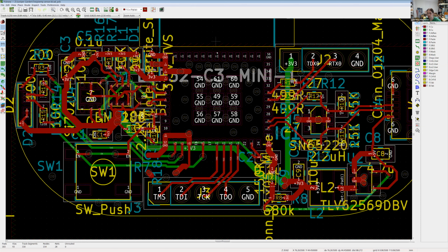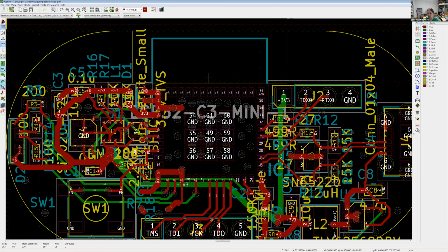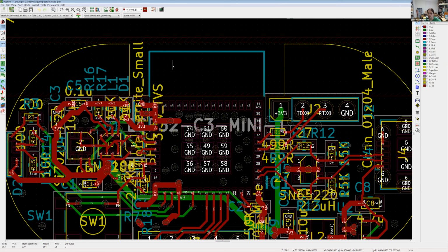The antenna, which is up here, it turned out that antennas have to have a clearance on either side of them so that they don't have any interference from metallic surfaces. So it worked out well to keep the shape of the device in this oval shape, and I could use the tabs on either side to protect the antenna from bumps and physical damage.